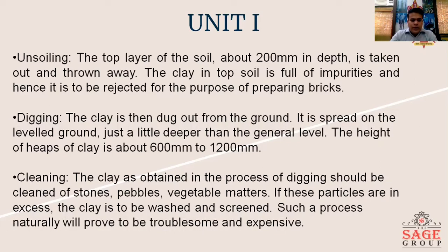Cleaning. The clay as obtained from digging should be cleaned of stones, pebbles, and vegetable matter. That means the impurities present in the soil spread on the level ground should be taken out. No stones or pebbles should be present in it. If present, they need to be separated out because they may weaken the strength of the brick. If these materials are in excess, the clay is to be washed and screened. Such a process naturally proves to be troublesome and expensive.